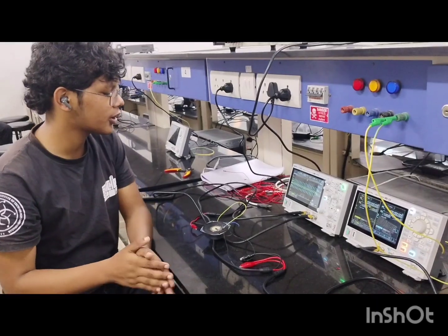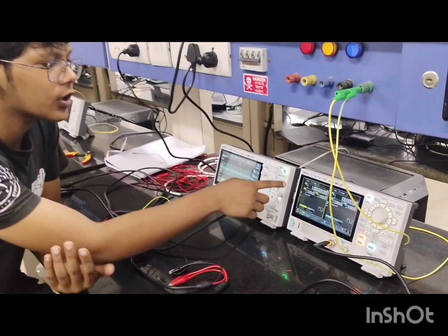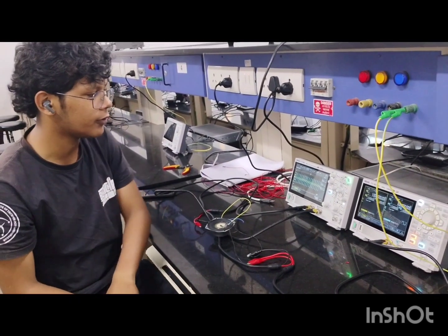In this experiment, we will analyze the magnitude response and phase response of two components, a piezoelectric sensor and a photodiode. We will determine their key characteristics, including the resonant frequencies of the piezoelectric sensor and the 3 dB cutoff frequency of the photodiode. So this is experiment 1 and we have taken a frequency of 1 kilohertz, amplitude of 5 dB and offset of 5.